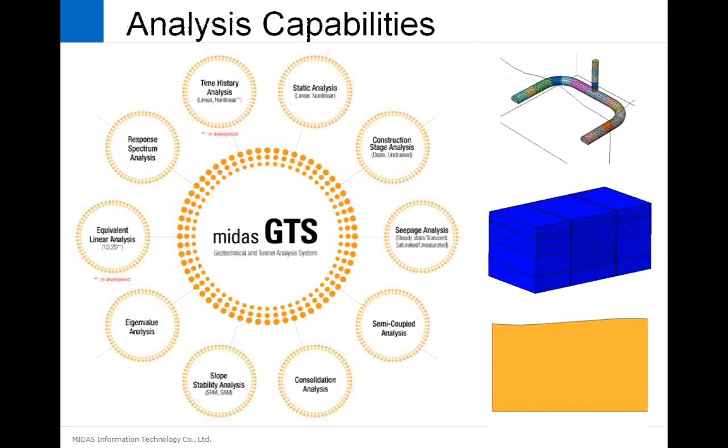Coming over to the various analysis capabilities which MIDAS GTS provides. In MIDAS GTS, we can do static analysis, both linear and non-linear. Construction stage analysis of drained and undrained type can also be performed in GTS. We can also perform seepage analysis of steady state, or transient seepage state analysis in GTS. In this, we can also account for the saturated and unsaturated nature of the ground.